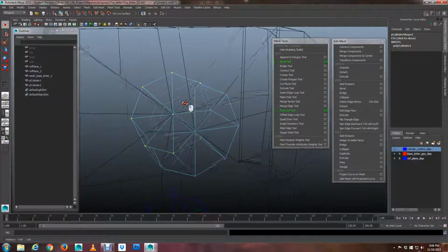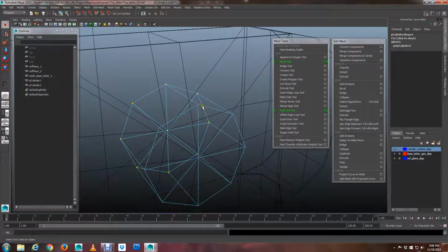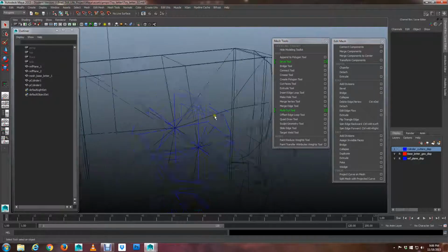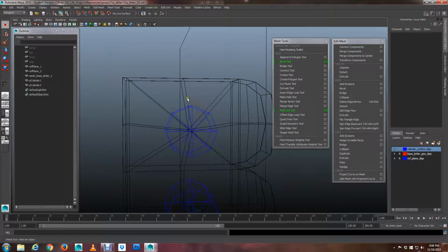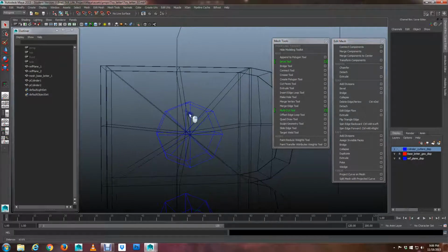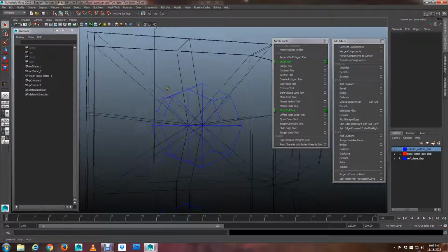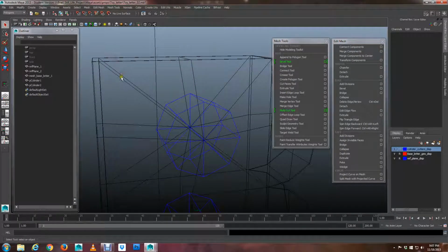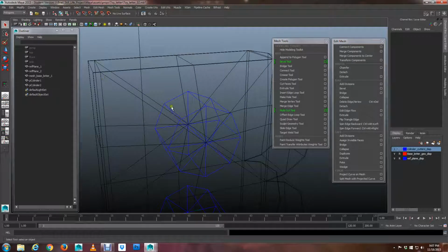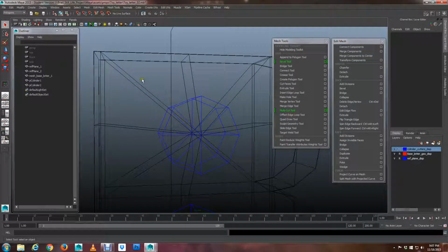So now what I need to do is add an outer rim to this cylinder here, because when I go to connect this up to the B shape, remember, when I smooth out the B shape, I want this to be a nice perfect circular shape. So I want to have an extra edge loop out here to be getting pulled on by these vertices, because again, when smoothing happens, all the vertices look at each other and they calculate the distance. They average out the distance. So this vert is going to be pulling on this vert, and this vert is going to be pulling on this vert.